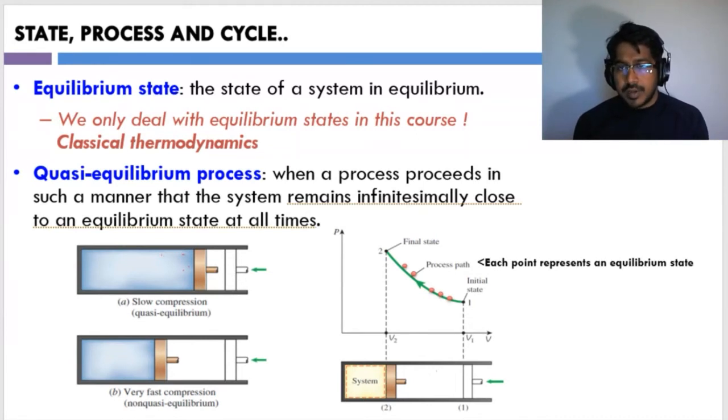Engineering is always about compromises, right? When you machine a shaft, you can go to the most precise shaft, like 0.001 millimeter tolerance. You can do that. You might feel better, but your company might not, because to machine that accuracy you need precise equipment and you need to pay more, and the finances of the product you develop will not work out. Similarly, in thermodynamic analysis, in certain cases the high level analysis is enough.